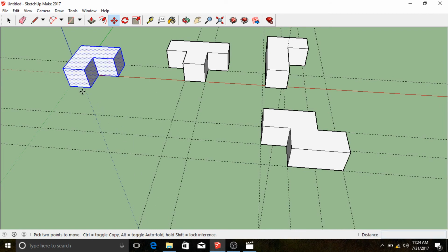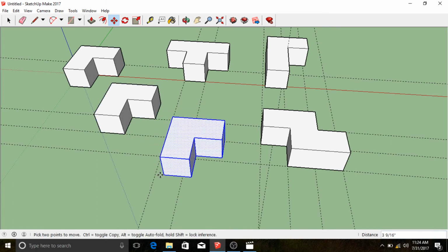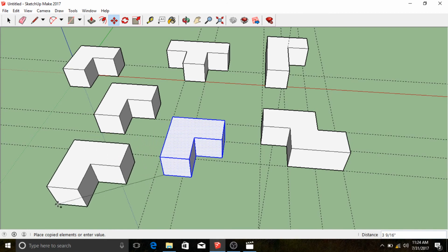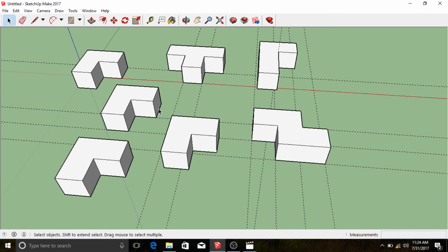another. But if you start the Move tool and you hit Control, you can see we have a little plus sign that just showed up on our cursor. And instead of moving something, we'll create a copy of it. And that's how I almost always copy, is within the Move command. I can do it again. And again. Okay, so just really quick, efficient ways to create copies. And then I can just modify these 3 blocks to make the rest of our shapes.